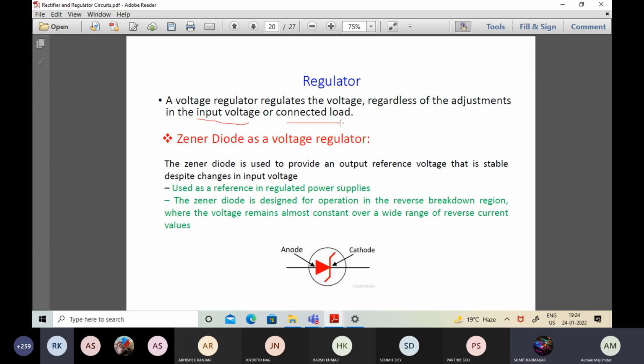What you have to understand at this particular point of time is this: Zener diodes have a very high dopant concentration. That is the first thing. The second point is that the carrier transport process effective in a Zener diode is through quantum mechanical tunneling of electrons, not the one encountered in normal diodes.